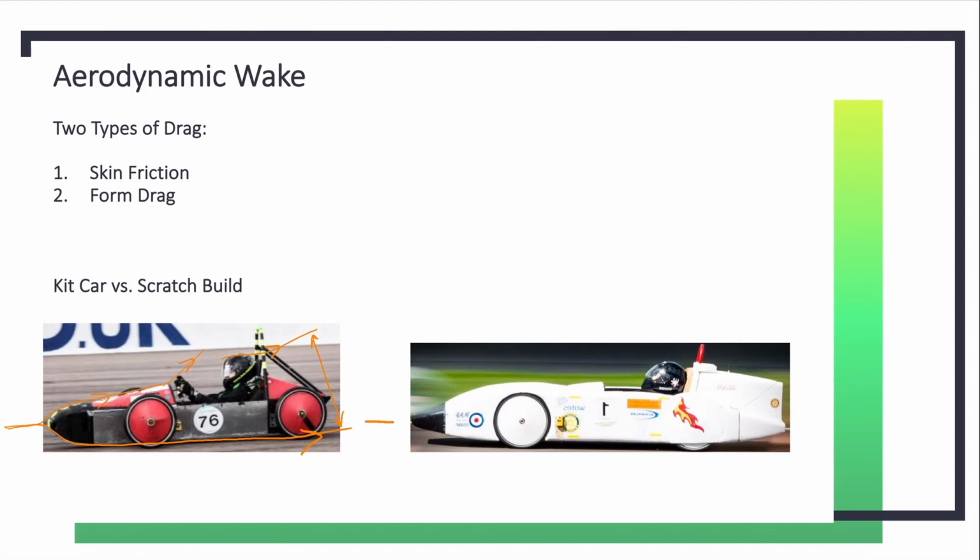You're likely to have flow over the top of the car. There's a little bit of a flip directing it to the helmet. Maybe a little bit of separation here, but you have a fairing. Flow going to the rear and then separating off like this. On the underside, you're likely to have flow coming underneath, staying quite nicely attached, and then separating there.